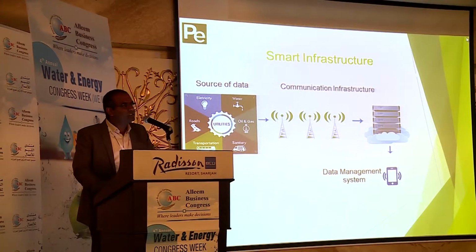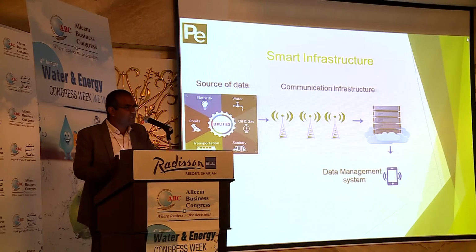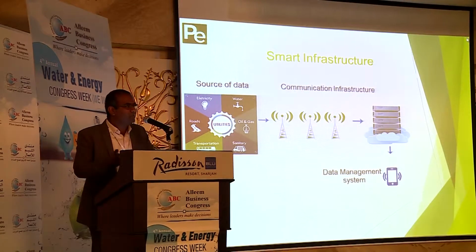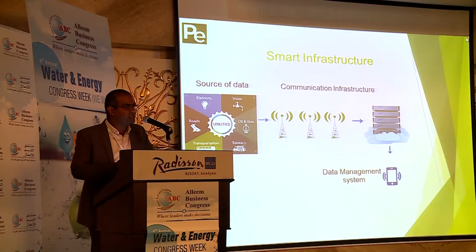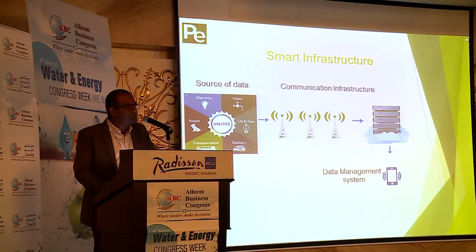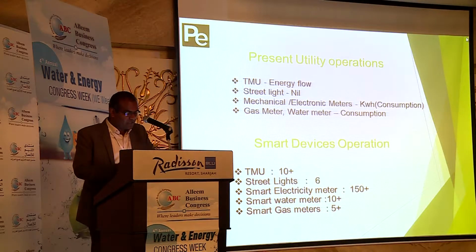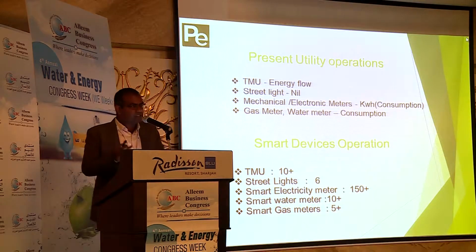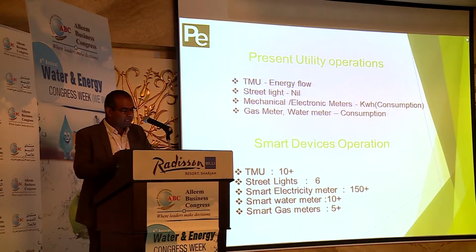Then the communication infrastructure can be selected by the utility according to their requirement. It can be RF, GSM, GPRS, PLC, BPL, LoRa, or Sigfox. Then we need to integrate this data in the master control centers where we can do data management.